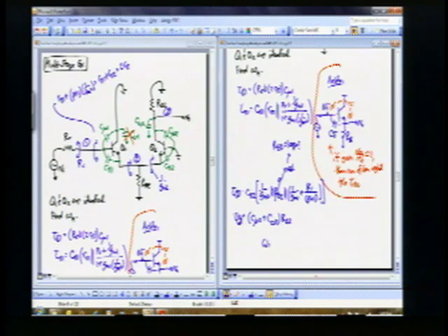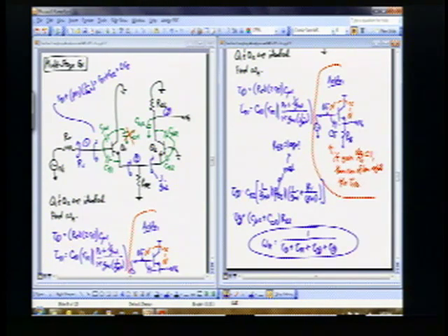And so now omega h, I can write the whole formula. Just add up all the time constants: tau 1, tau pi 1, tau 2, plus tau 3, and 1 over that becomes my corner frequency for this amplifier.